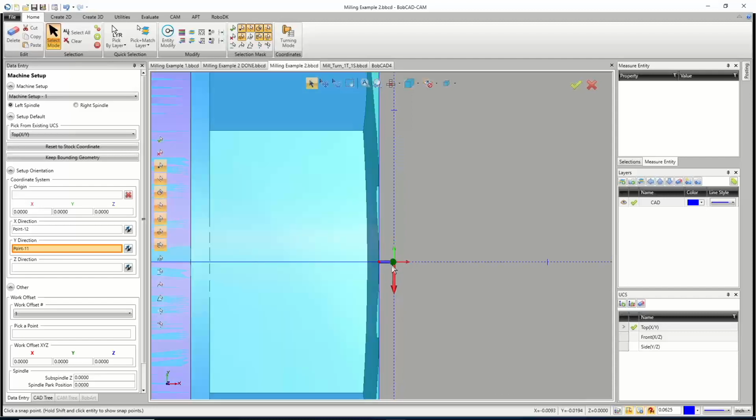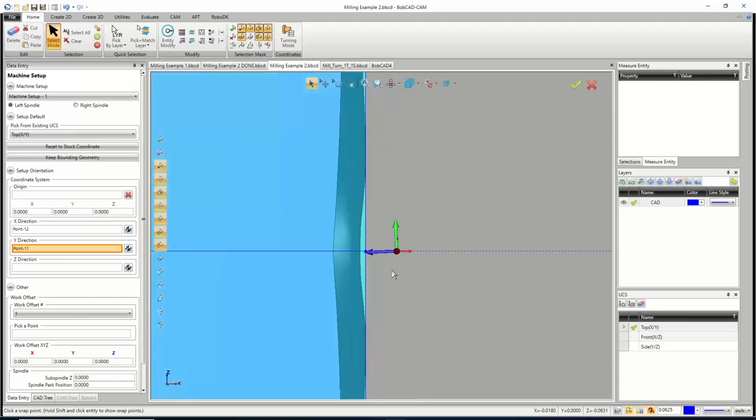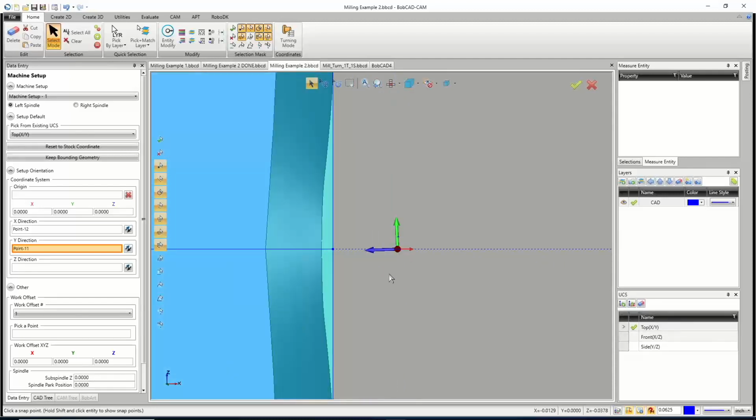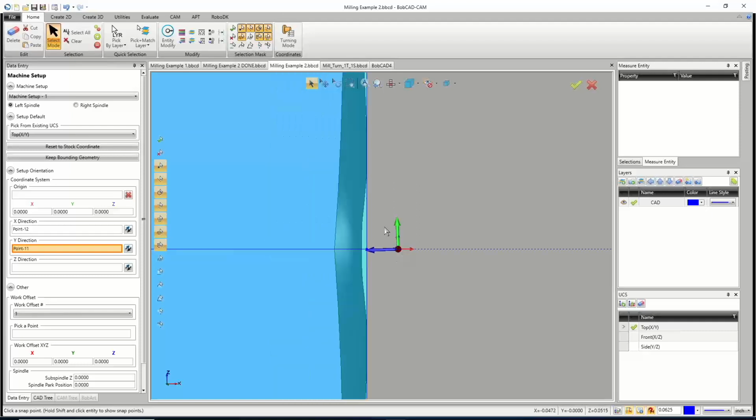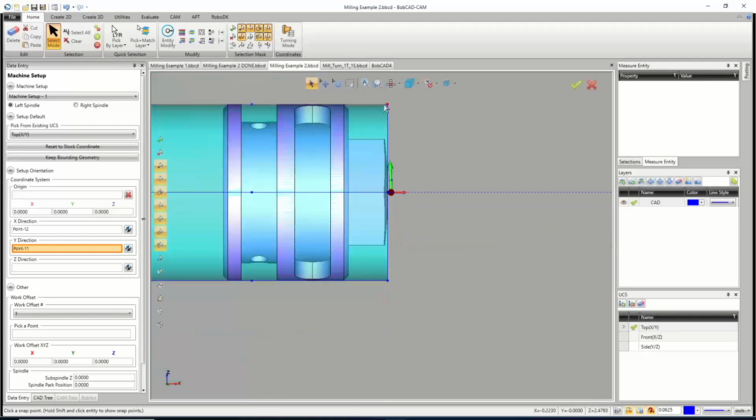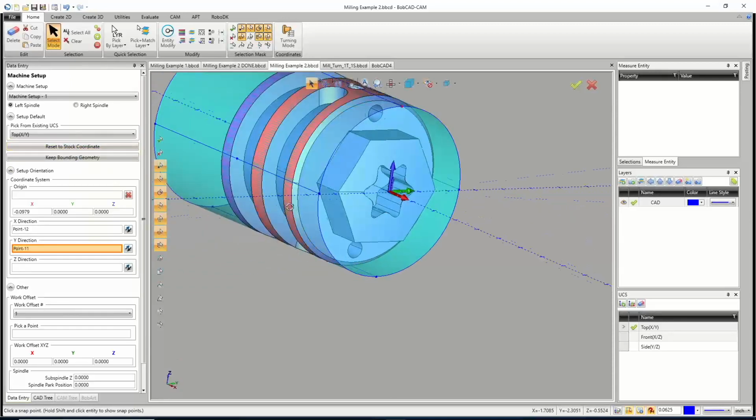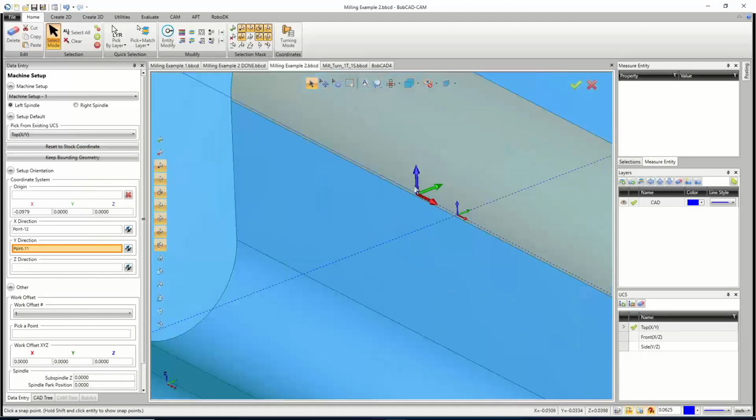And it's tough to see, but maybe if I go to that view, there we go, a lot easier to see there. My coordinate system is not square to the front face. It's got that tilt to it because I'm pointing at the point up above, so it's on an angle. So I need to reset my coordinate system. All right, that puts it back. And then I need to make sure that it picks the front face, not XYZ0. I need this little 90 thou accounted for, or I would need to add that into my face geometry.